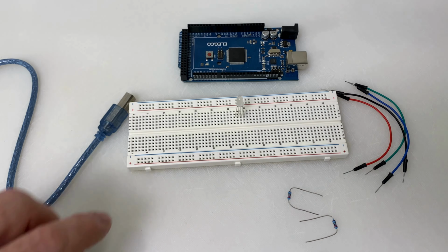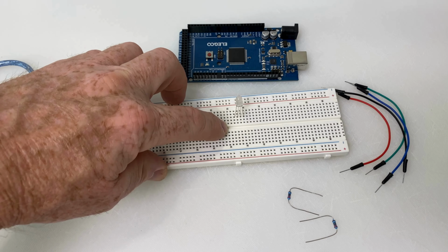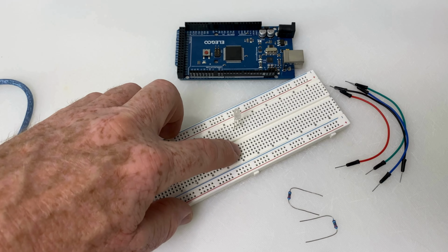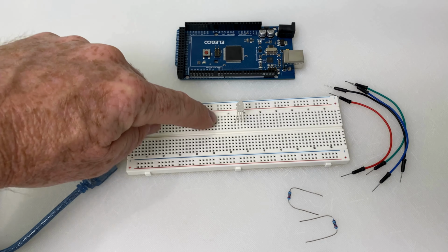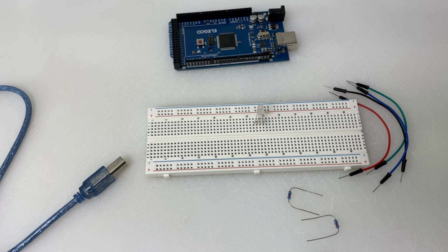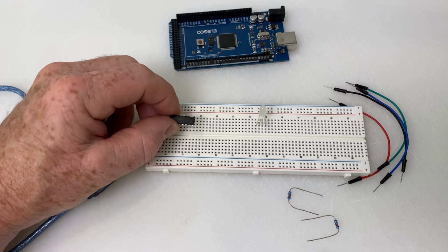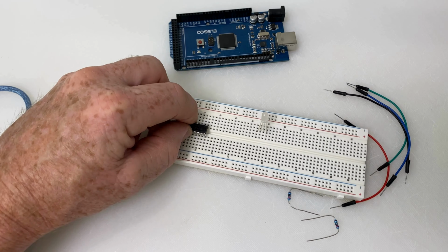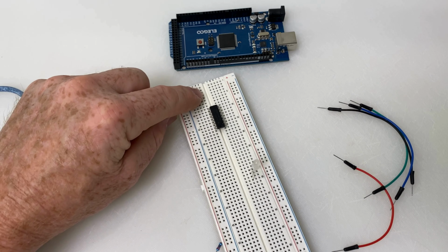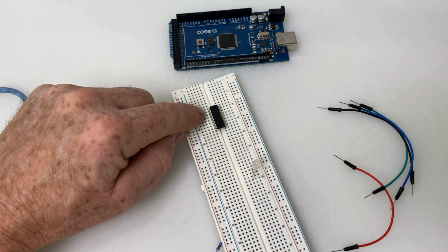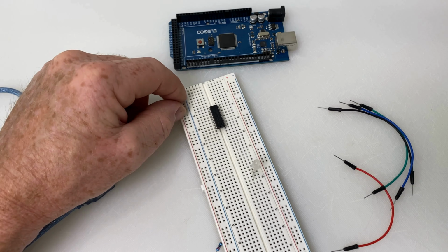Another important part of the breadboard is the center channel called the gutter. This isolates one side to the other, so all these rows here are separate to all the rows here. The handy feature of having that gutter is you can place an IC over the top like that, and each of the pins is accessible. One set from this side and one set from that side. Because they're isolated, they're not shorted out.